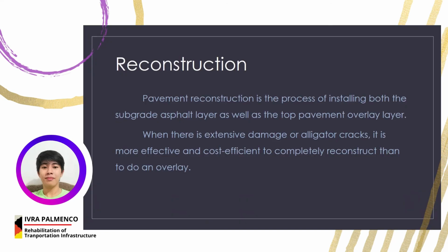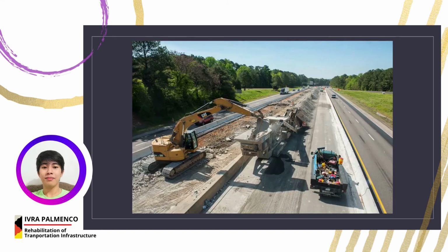Another method of rehabilitation is reconstruction. Pavement reconstruction is the process of installing both the subgrade asphalt layer as well as the top pavement overlay layer. When there's extensive damage or alligator cracks, it is more effective and usually cost-efficient to completely reconstruct than to do an overlay. Basically, reconstruction follows the same steps and principles as resurfacing.